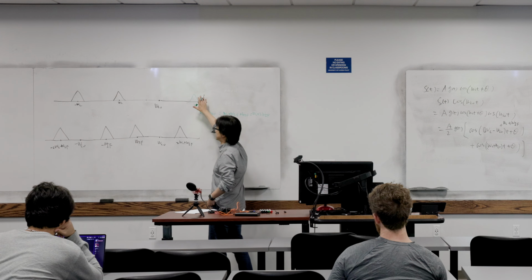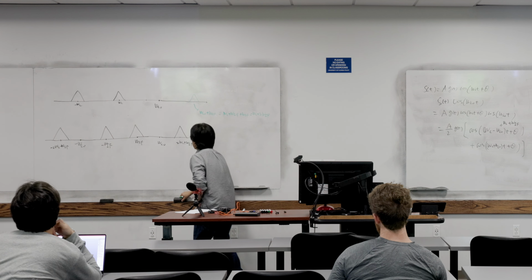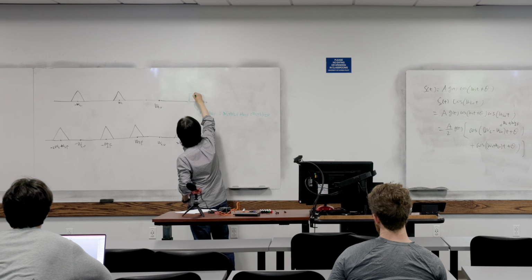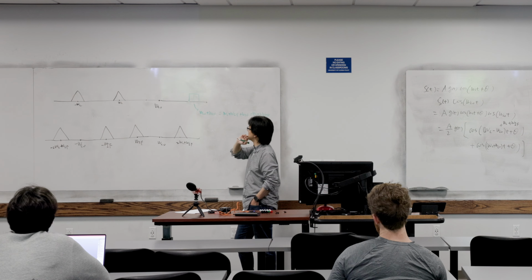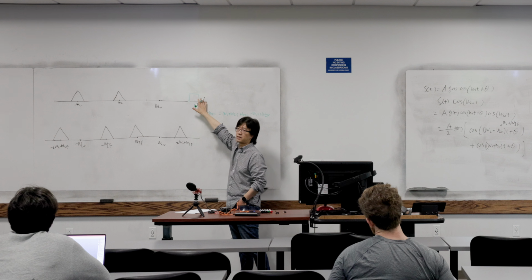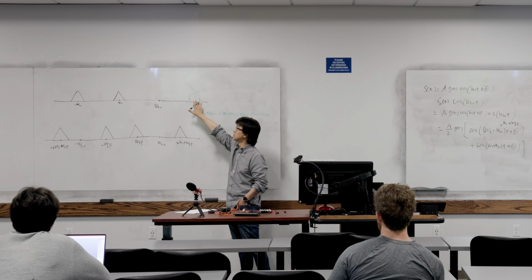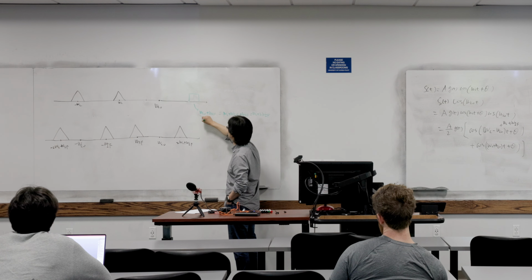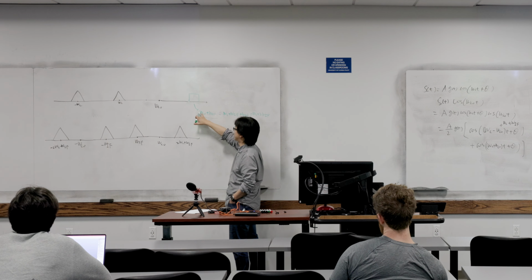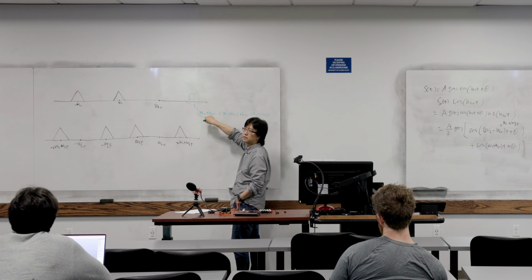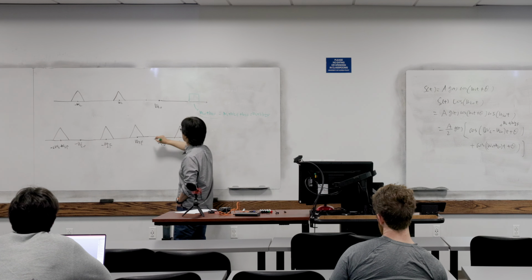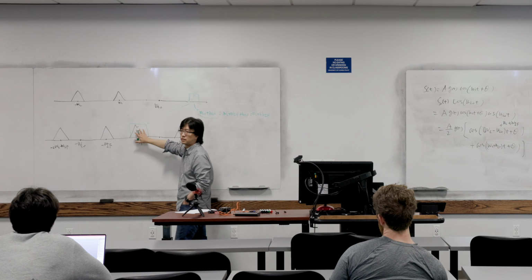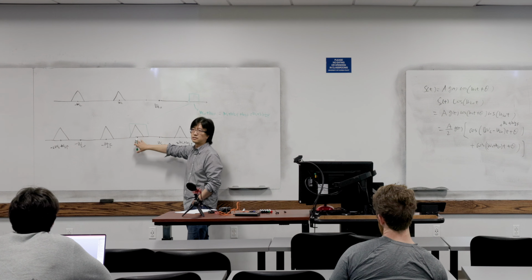Okay? What if we have a signal here? Maybe let's draw the signal in a different shape to indicate that's the non-desired signal. After shifting this guy by an amount of WLO, where will that signal be in this picture? So here is this guy. If we subtract WLO, it will become WIF, that is here. This signal will be shifting here. And the WIF is our desired signal.